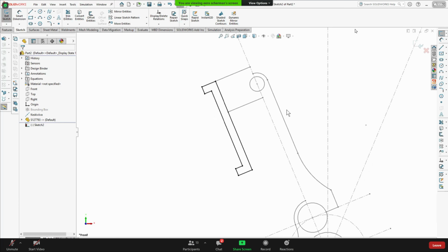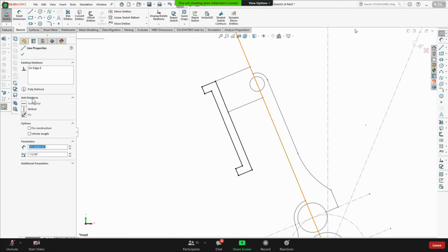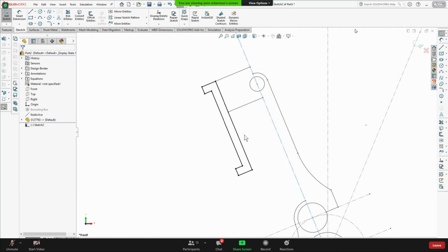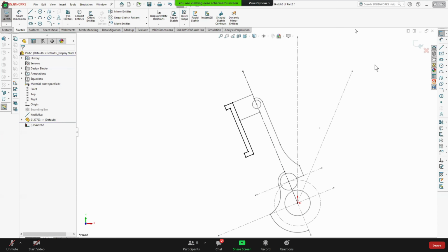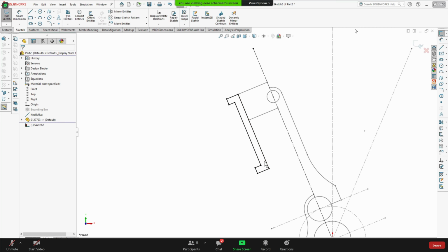And of course, in order to create a revolved feature, I need a center line. The center line of the revolve is that one. So convert that one and make it a construction line, so it actually works. So did you just replicate those sketches on top of the existing sketches, or did you just change their properties? I replicated exactly the same geometry here. Oh, so we have two sketches, one on top of the other. Yes. Great, thank you.